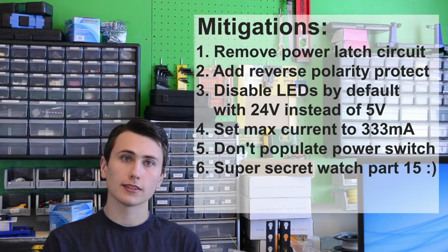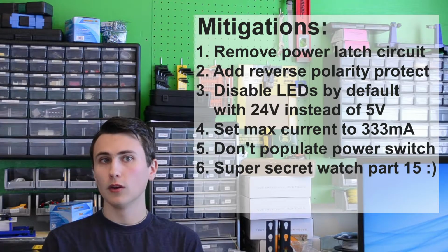Now those are the critical design issues, but from a risk perspective, we still aren't quite done. The PlantLight has no feedback for when LEDs get hot. If the fan were to fail or the heatsink was not installed, we would have no way of knowing.